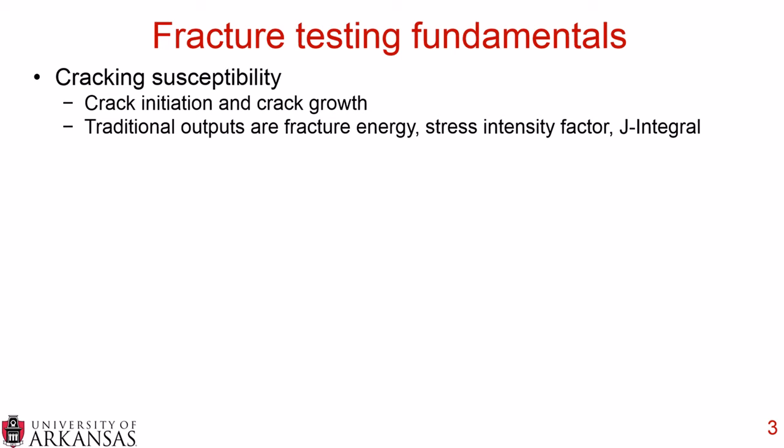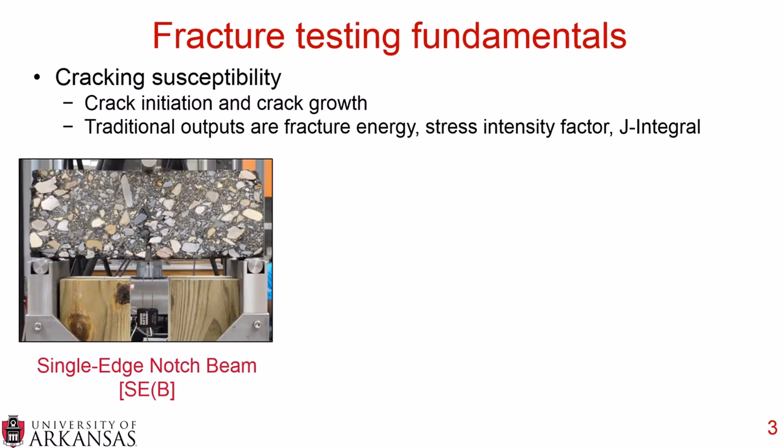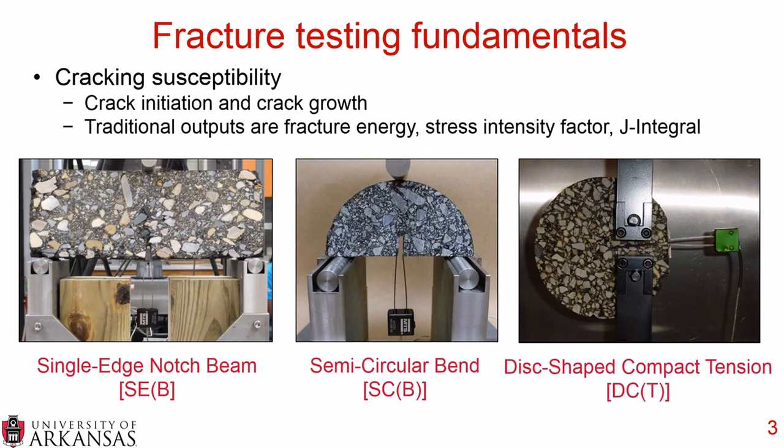And there are different fracture testing geometries. You have the single edge notch beam, which is shown here. You also have a semicircular bend and a disc-shaped compact tension. Now, while there are different geometries, all of these tests can capture fracture energy, stress intensity factor, and J integral.